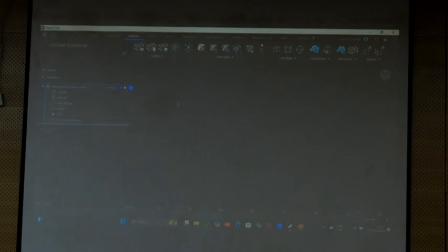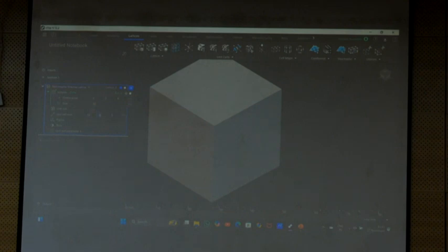So just type it here, okay. Double press on it so that you can see the available options, or otherwise just type what type of design we want, like cylinder or sphere, cube or something. Suppose I need a cube, I will type it here, and it automatically gives you the cube, see, there it is giving cube, right. It asks what size of cube you need, the cube position is horizontal, origin I am not changing, what is the size of the cube. So I will take 30, okay, 30 cube. This lattice size I will increase because the processing time gets reduced. So I will take it as 10, 10, 10. Let's see.